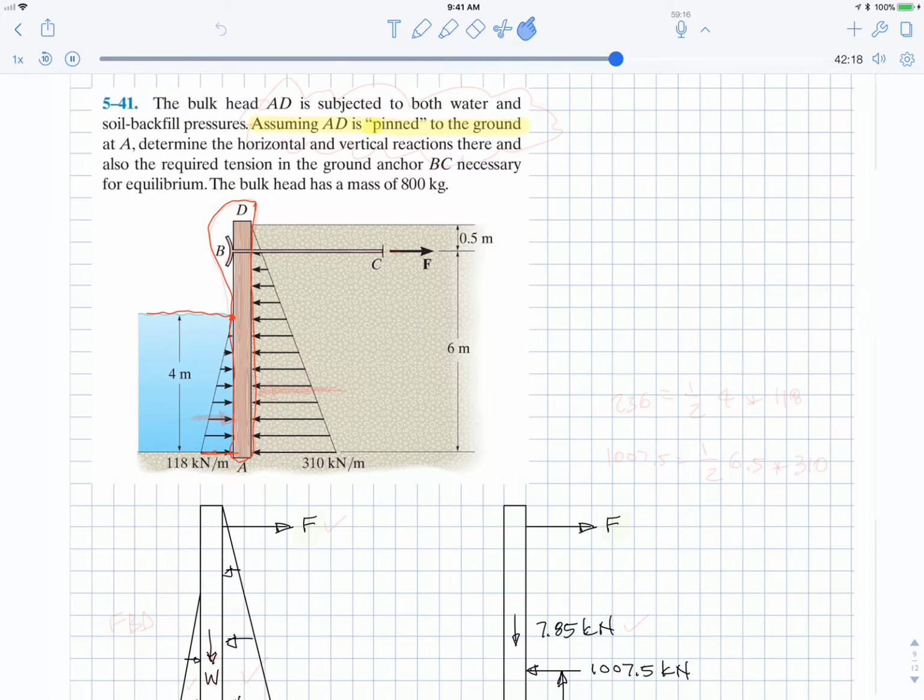And so you can see here, you've got some kind of force from the water, I'm trying to eyeball the centroid of that blue triangle, and then you've got some kind of force here, the centroid of that brown triangle. And those are not going to add up to zero. It's going to want to flip over, and to make everything in equilibrium, they tie back this wall this way.